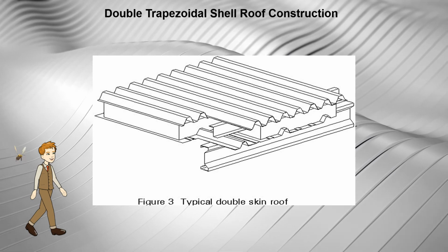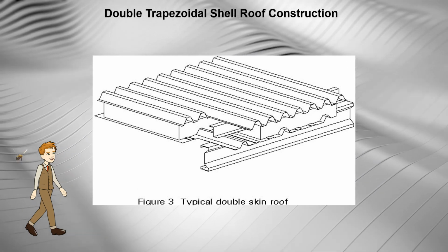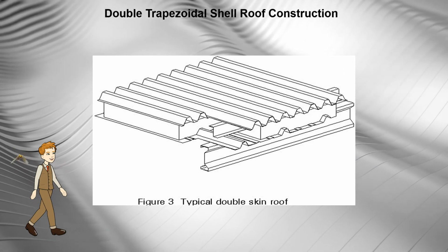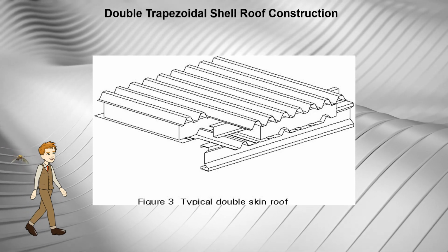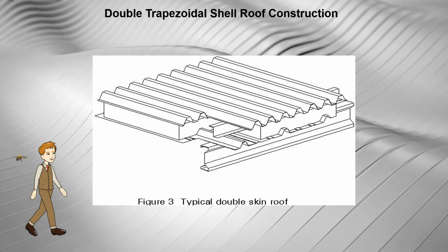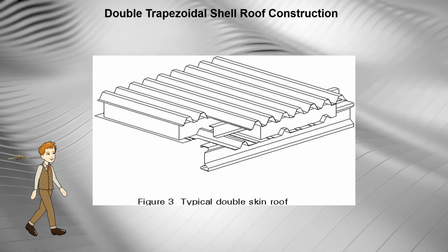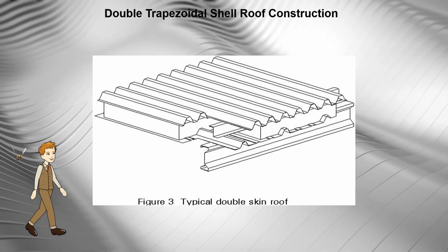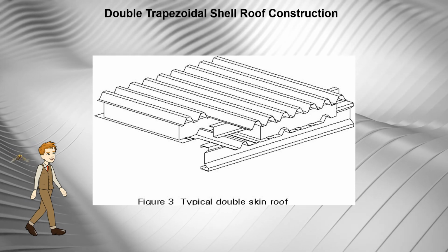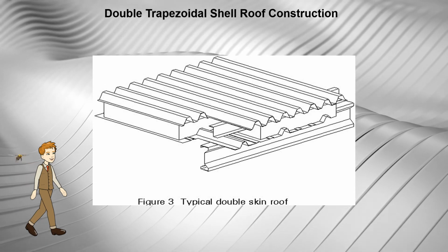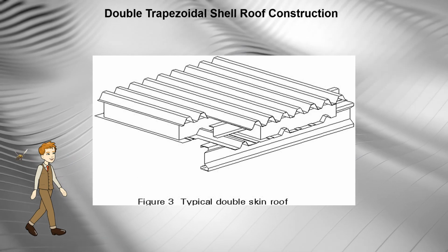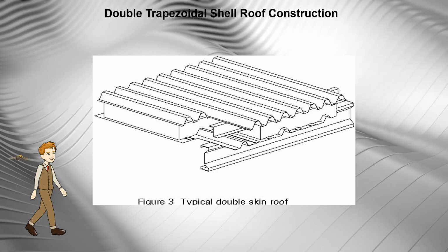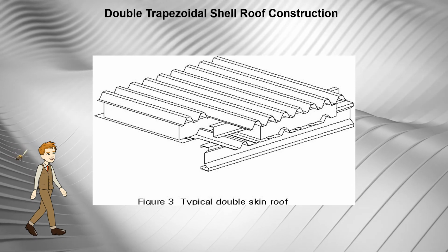Sealing of the liner skins or addition of a vapor barrier and breather membrane can be employed to improve performance in situations where there is a higher condensation risk. Manufacturers normally supply a coordinated range of accessories and roof lights to match their particular profiles. A typical construction of the system is shown in Figure 3.